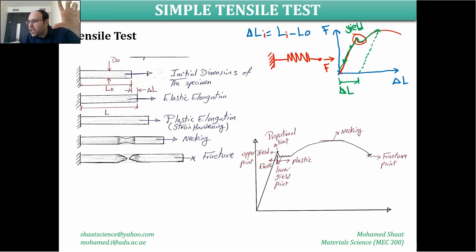It means that the yield point is not clearly seen. There is no specific yield point, and in that case, this material will be qualified or named as a material without yield point phenomena. But the yield behavior is still there. It is not clearly seen in the curve, yes, but it is still there that distinguishes the elastic from the plastic behavior of the material.